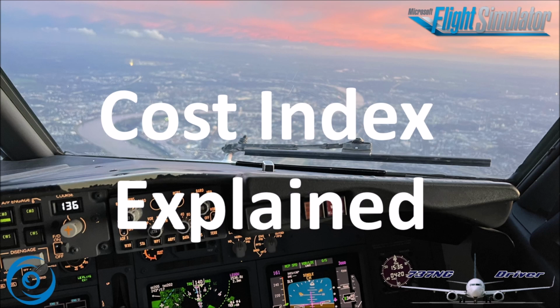Now, let's actually have a look at an analysis that Boeing has done for a particular non-named operator of the impact both in trip time and annual cost savings by adjusting the cost index. The operator was using a cost index of 45 on the Boeing 737-700 and on the 737-400 cost index 30.